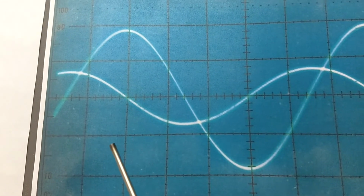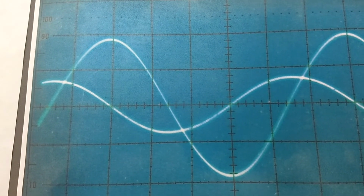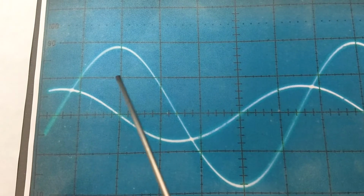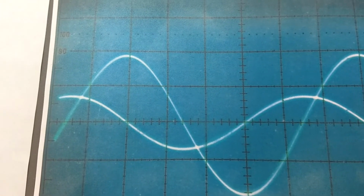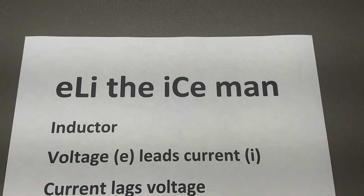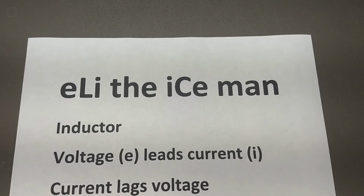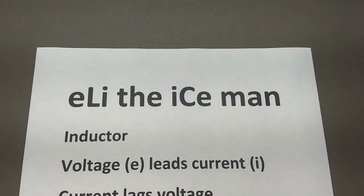And again, it doesn't matter what frequency, it doesn't matter what the value of the capacitor is. When it's a sinusoidal waveform, this 90-degree phase shift is always the same. Now those phase shifts will become important as we go on talking about inductors and capacitors.